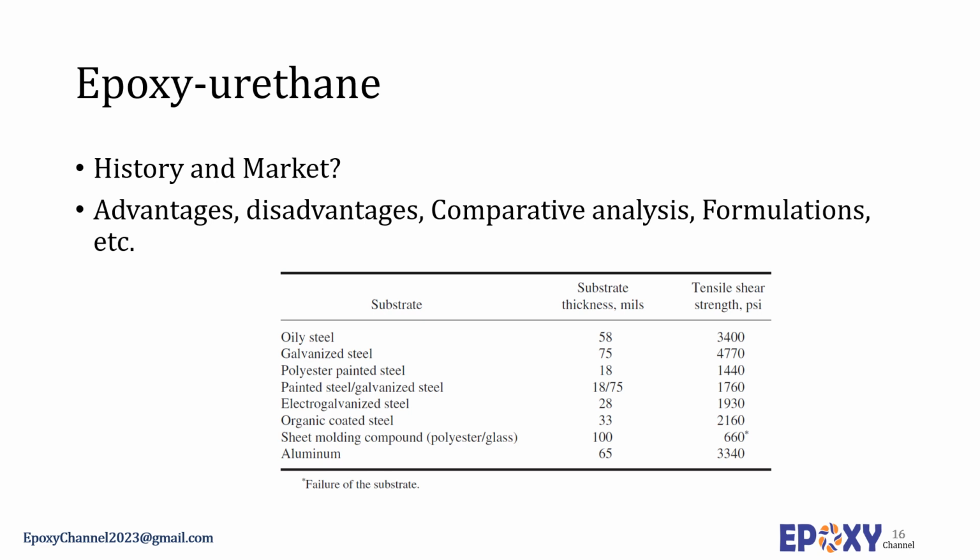Epoxy polyurethane adhesives have a great deal of toughness. They have high elongation and very good peel strength and impact properties. They also have a relatively high degree of tensile strength given their elongation. These adhesives bond well to flexible substrates such as plastics. They also bond well to oily surfaces. The main market for epoxy polyurethane adhesive is the automotive industry.